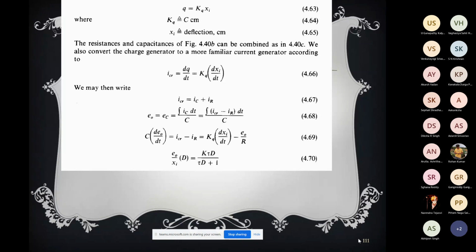After some time, you can take the measurement, which is E0, and from E0, you can calibrate to know the displacement. If you can calibrate to know the displacement, you can calibrate it to know the velocity, and the acceleration. Also, the displacement is proportional to the applied force by means of the stress strain law. If you know the material and the force versus displacement nature of the material, from there you can also measure the force and not only the displacement. Similarly, pressure is the force divided by the area. So if you know the area, you can also know the applied pressure. All those things you can know from this transducer.